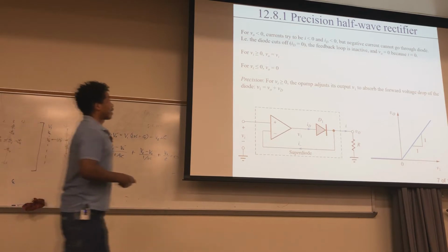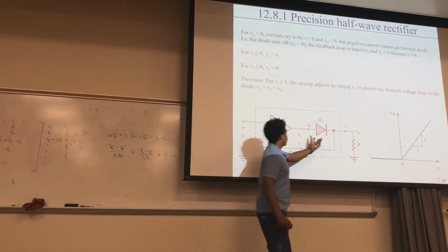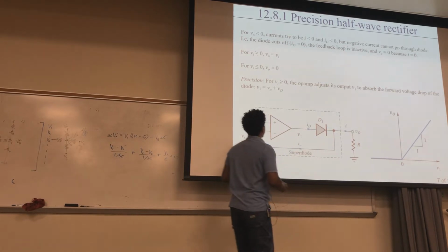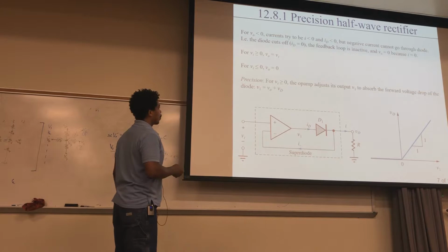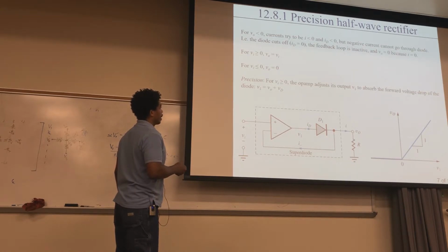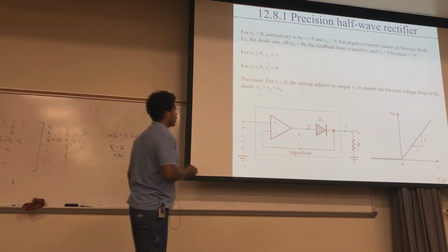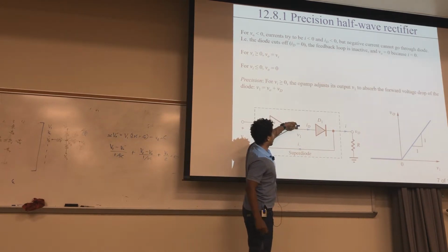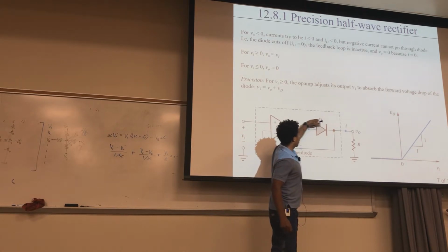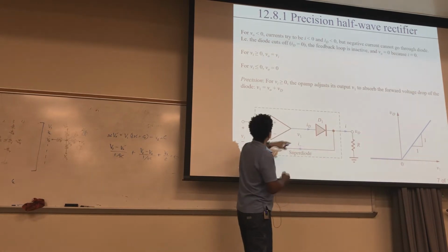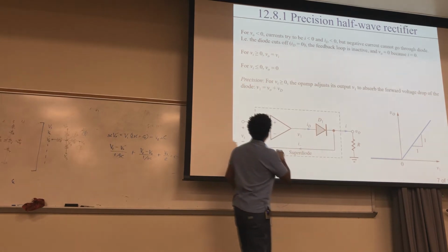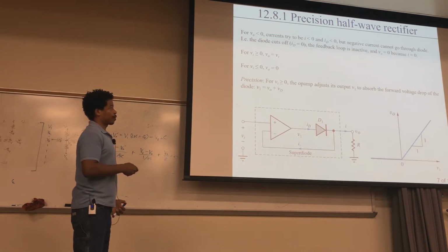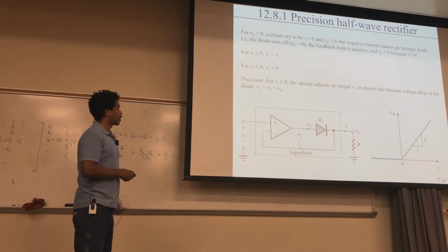Okay. Oh, and another thing, what happens to this voltage drop here? Let's call this voltage drop Vd across here. The voltage at V1 right here accommodates both of these. So you can take this voltage to be Vout plus that voltage at this point. And then as you go across here with a drop of Vd, the voltage right here will be this voltage minus Vd, which is just Vout. So that Vd is being absorbed into that V1. Okay.